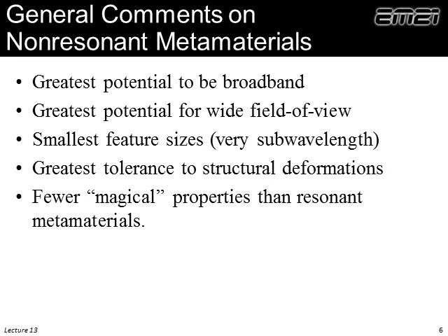Also, I think these have the greatest potential for having a wide field of view, again going back to the non-resonant nature. These certainly have the smallest feature sizes. As I mentioned, the period of the lattice can be a millionth of a wavelength, and they will work just fine, assuming we can make something that small. In my experience, these are the most robust to structural deformation, so anytime we manufacture something, it does not come out looking perfect. These are very robust to that.